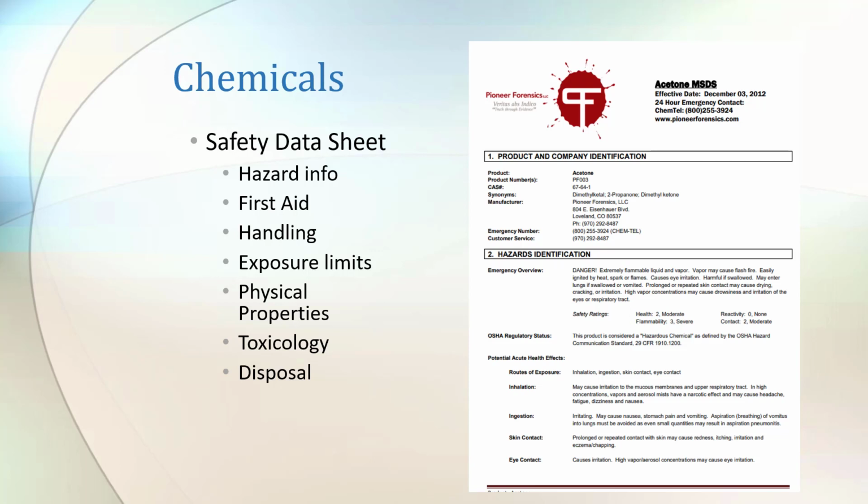So this is a safety data sheet. As we look at it, it has 16 parts. It goes back to the Globally Harmonized System, GHS, where all the world went to these. Before they standardized them, any chemical company could make up their own format, and we'd get them from all kinds of different countries in different formats. Now all of them are formatted the same way. There's pictographs. They all have the same type of pictures. All the pictures mean the same thing from country to country. That's some of the information that's on it.